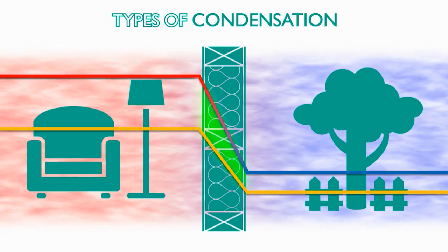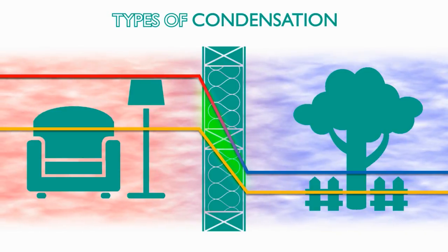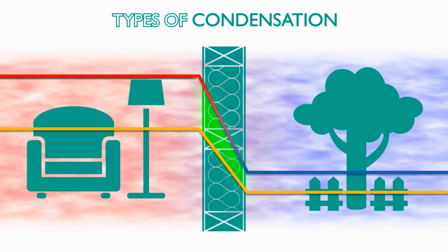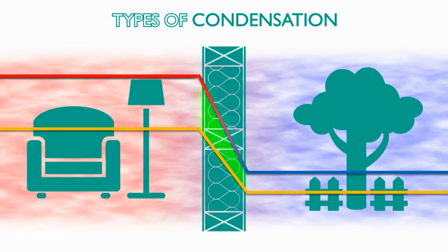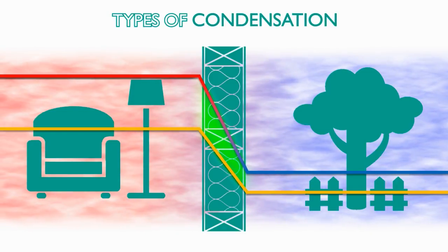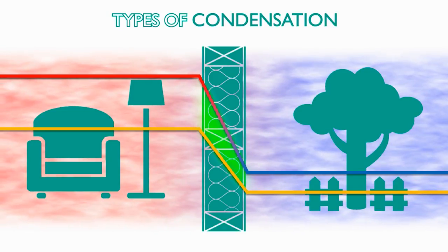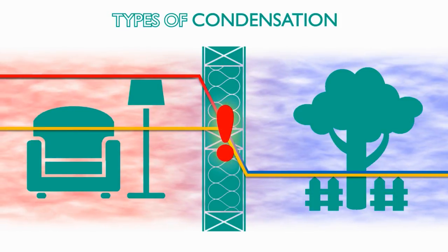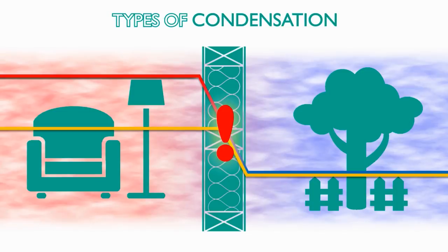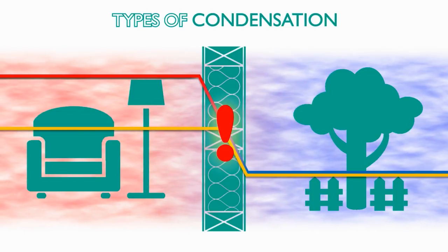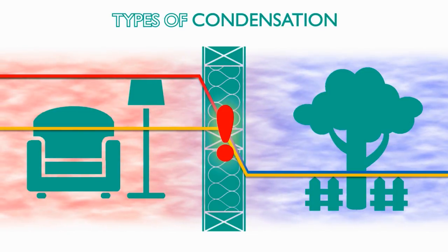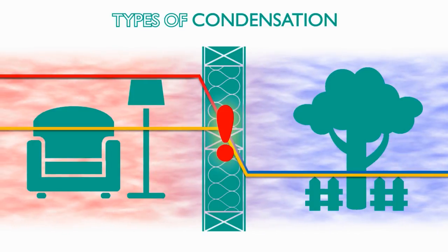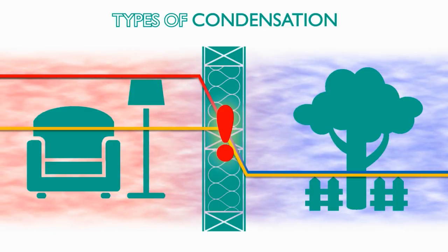Provided the actual temperature remains above the Dewpoint temperature, there will be no significant risk of condensation occurring. If the actual temperature drops low enough to coincide with the dew point, the air will become saturated and the condensation will occur at the point the temperatures meet. The nature and severity of the condensation problems will be determined by the extent to which the temperature drops below the dew point and where in the structure this occurs.